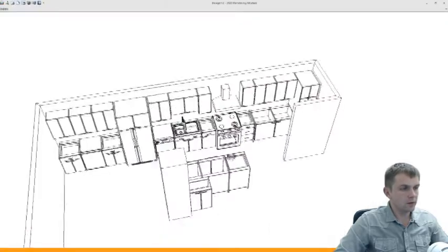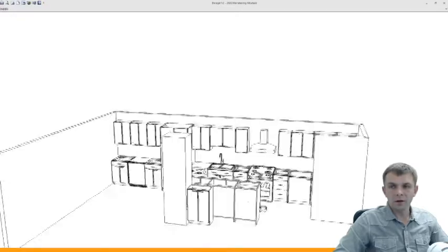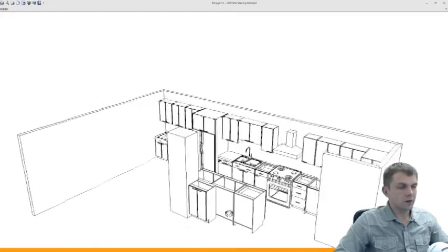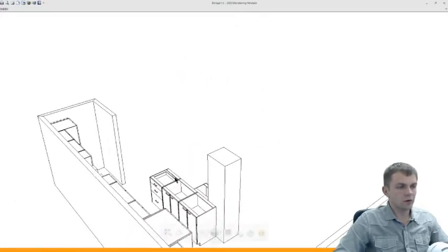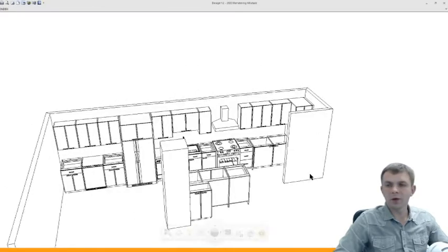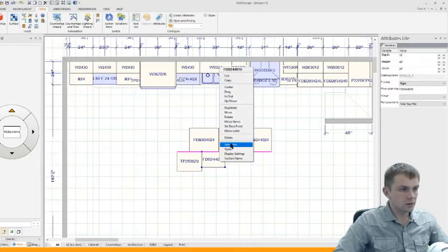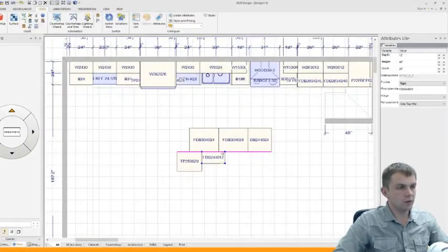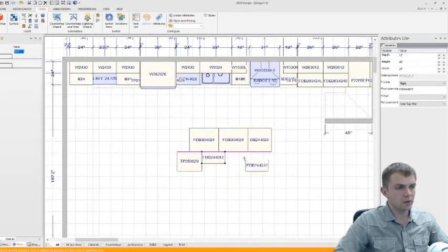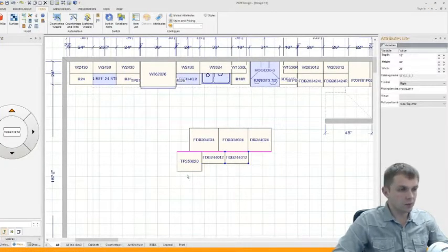Basically what I wanted, so this is a 40-inch high bar height island, and the idea is that people can sit here. Also I created a nook here, so they want to overhang the countertop so they could have a person sitting here while they're prepping on it or entertaining. So let's continue. This one has to be only 12 inches deep, so you have a 12-inch overhang, and you can put some bar stools on the front, and then everything lines up nicely with this post.